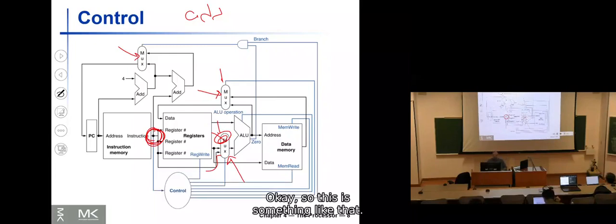What was your name? Megan. Yes, okay. The instruction is 32 bits, and the first 6 bits, the most significant bits, are the opcode, and the last 6 bits are the function code. These 2, opcode and function code, will tell the processor what the sources would be, okay?